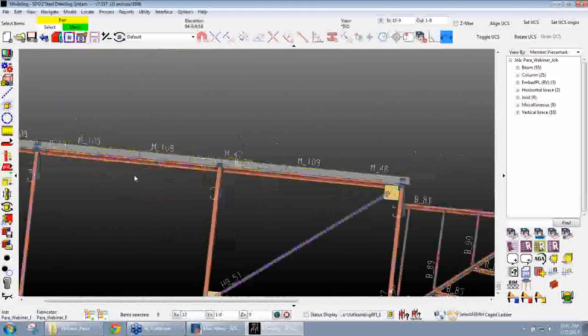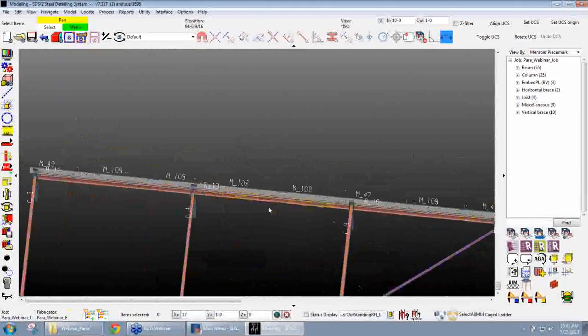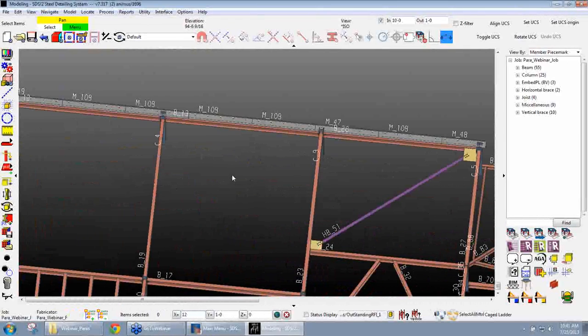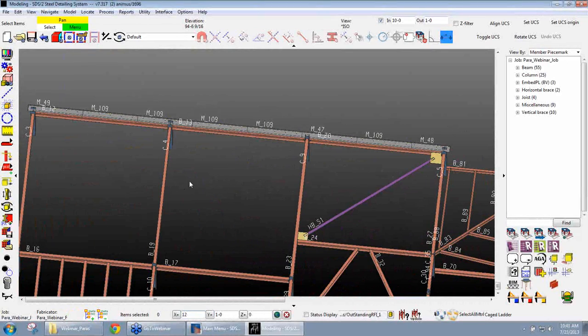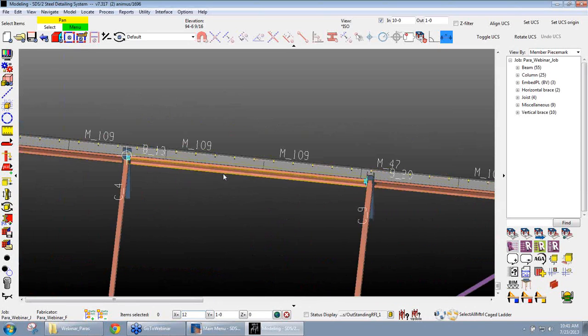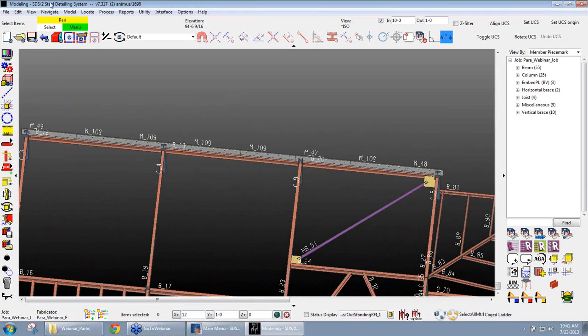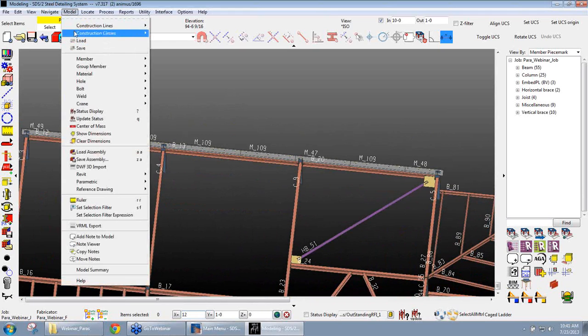So like I said, that's just one version of that bent plate pour stop parametric. Another good thing to know here is the ability to erase a parametric. If you do mess up on running a parametric, you need to rerun it, re-enter values so revision came back. You could go through and manually edit the materials and change it from there, or you could erase the parametric. So erase a parametric, very simple, just like running.